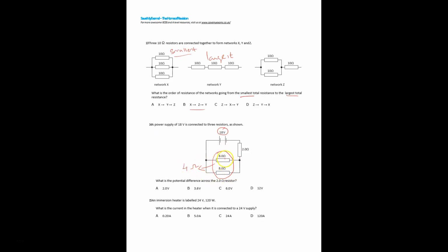How do we know? Here 8 and 8, this is applicable if the two resistors have the same resistance. So what is the resistance value? 8 ohm. Are they having the same resistance? Yes. How many resistors are there? 2. So you divide the value by 2, you will get the result. This is the combined or total resistance here. So now I redraw the diagram, same diagram.